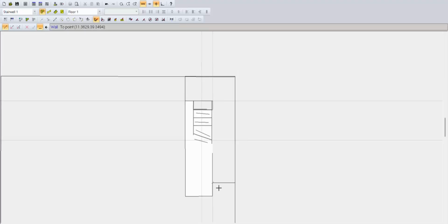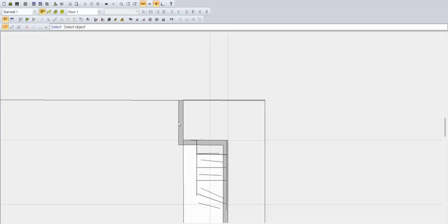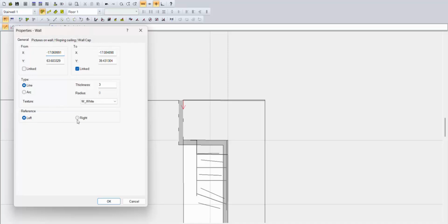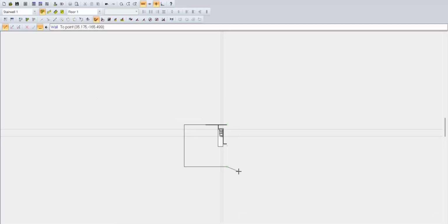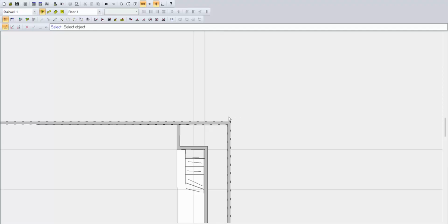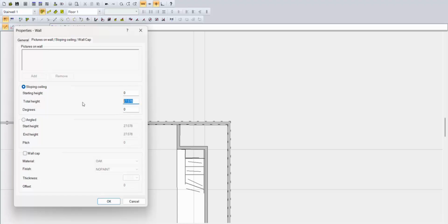They are quite helpful. So I'm just drawing maybe some walls. When I draw a wall, I can say left or right from the line. So now actually I want to have them on the other side. So I see now my walls here, or I could draw longer walls. And you can also say to these things, like now I was drawing it, but I maybe want to have this not this height, but I want to have it at 120.